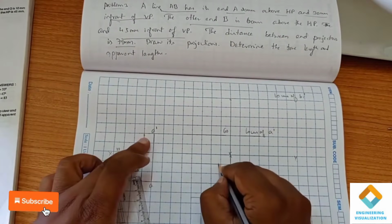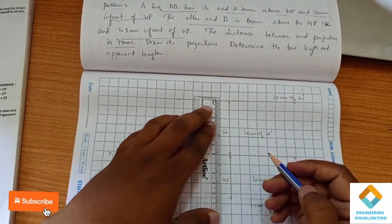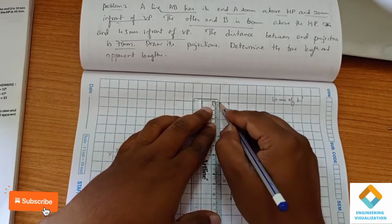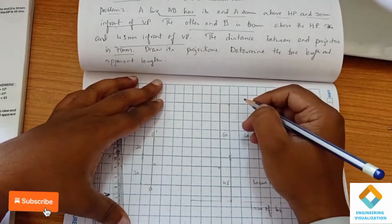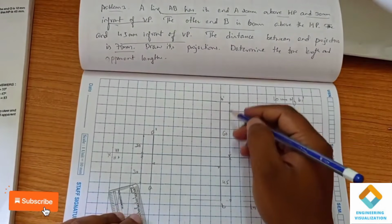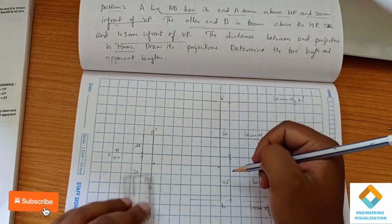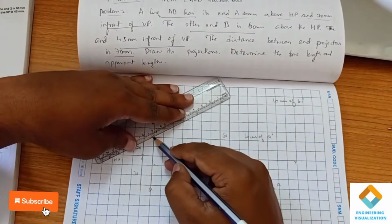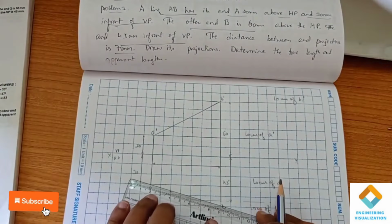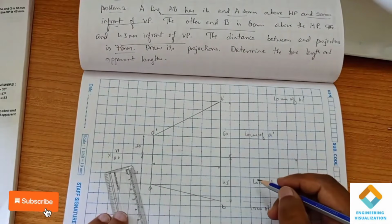So here the distance between end projectors is 70. So here I am going to draw a vertical line. Drawing it. So here I'm going to mention this is B dash and this is B. We know that as the apparent lines are drawn, the endpoints, if you draw a straight line, will be falling in a straight line. Okay, so that's why we're getting this B dash and B on the same line. So I'm going to join this. So this is apparent length 1 and this is apparent length AB. Okay, so these 2 points we're getting.